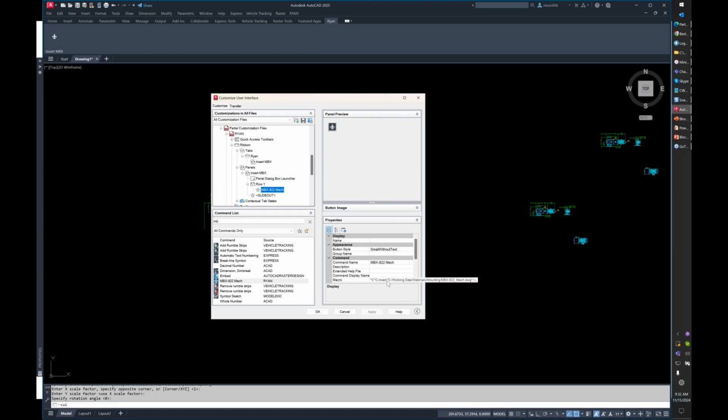So this is how we create custom content and custom ribbons, custom pull-down menus if you prefer the older style of AutoCAD or AutoCAD Classic. So those are all the different ways we can do block libraries and make them more effective, depending on how far you want to take it, right? Custom elements are nice up here. The problem is now you have to support this, right?